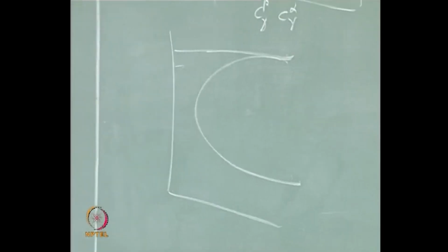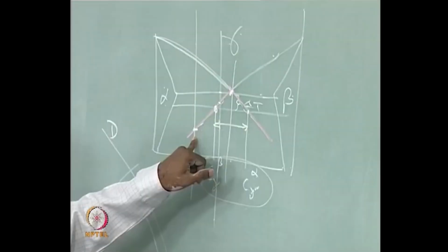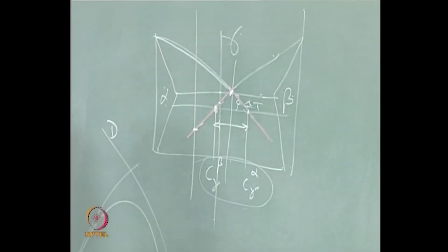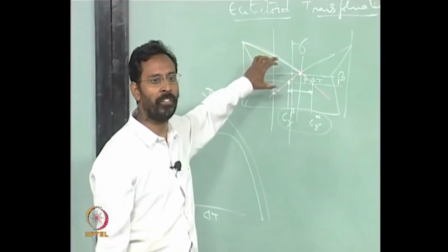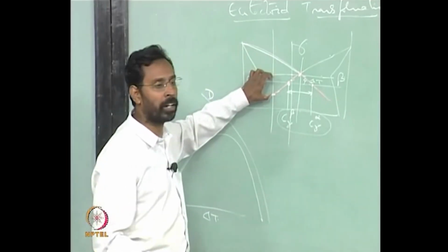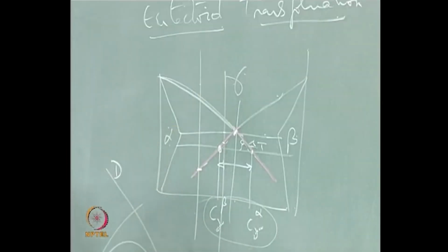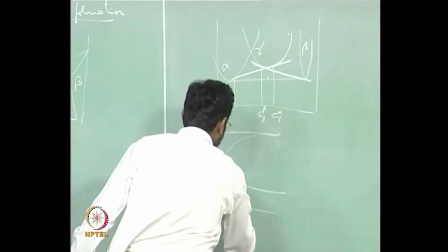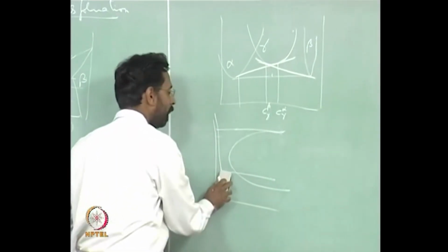But if I take this alloy, which is farther from the eutectoid composition, and I can undercool it, of course undercooling that alloy to that temperature is also not easy, because the extent of undercooling that I need to provide is very large. If I can somehow provide that undercooling and hold it at a temperature below that, you would end up in a bainite.